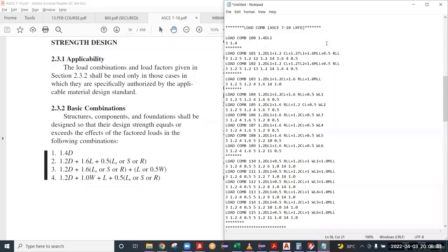You can add collateral load in dead load also, because if you observe all these combinations, they have not given anything specifically about collateral load. Because collateral load is additional dead load, you can apply the same factor as dead load. So that is 1.4. CL also you can mention here.